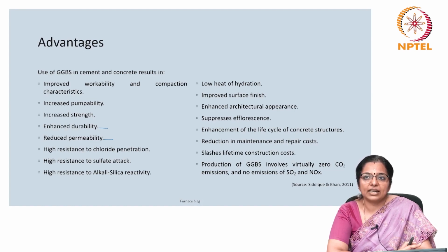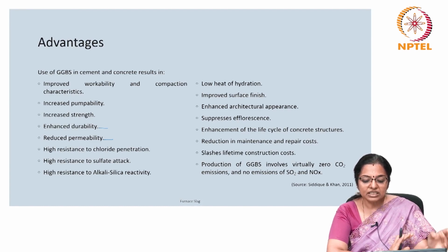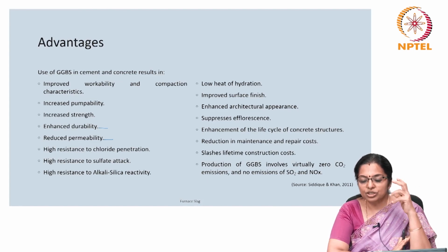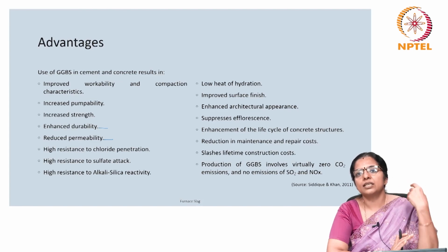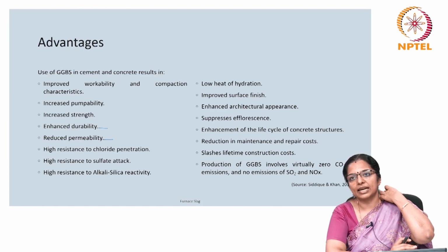Its high resistance to chloride penetration, sulfate attack and alkali silica reactivity ensures durability in diverse environmental conditions. Additionally, this slag results in certain more advantages, which is low heat of hydration. The improved surface finish and enhanced architectural appearance is an added benefit, especially for architects where aesthetics becomes a very important aspect in the design.